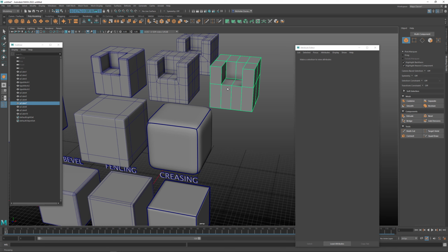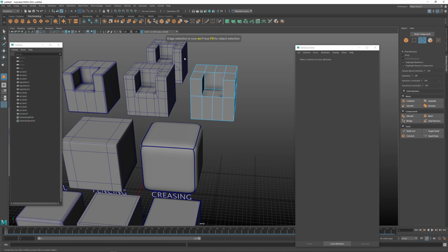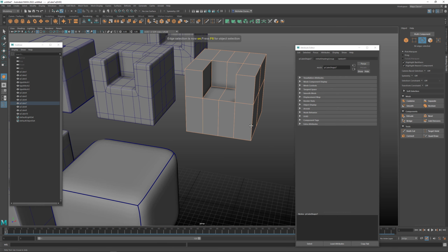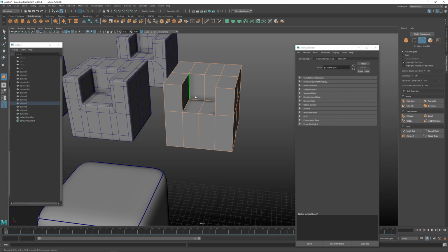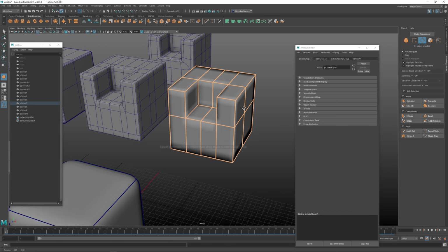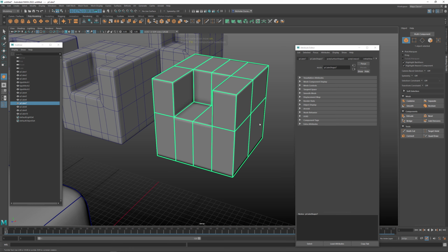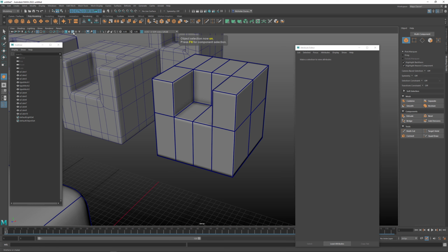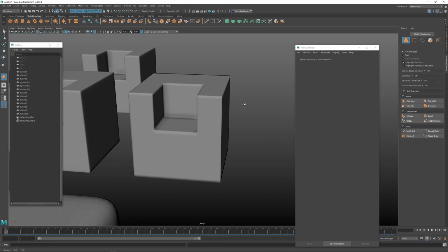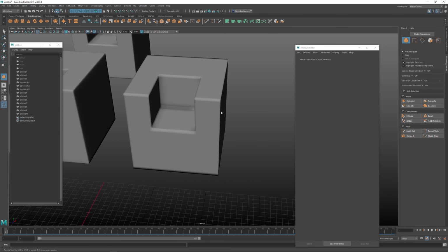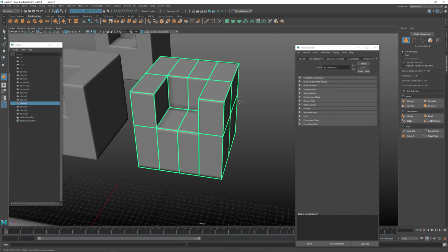Okay, so with this I'm going to hit F10. I'm going to select all the edges through here, and because we have this thing as a cube, we could shift right click, say crease tool, tap 3. Now that's going to hold hard edges for everything. This is what I was talking about, where I just do not like the way that it shades through this model. It can help if you hit page up for this, but it still doesn't look all that great. Let's turn off wireframe on shaded. So it has this kind of look. Again, not a big fan of how it shades the model.